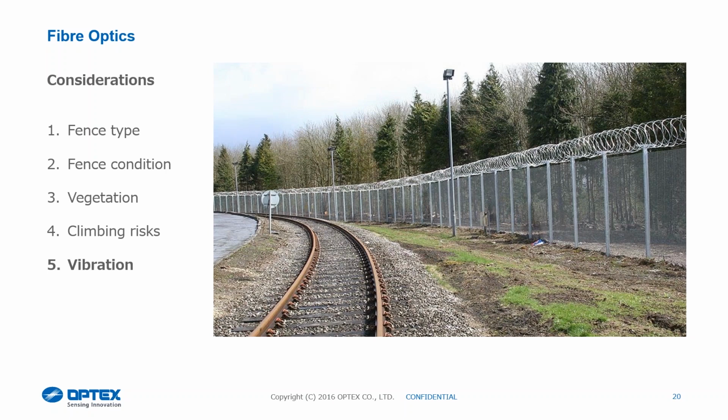We have had some sites where there have even been new fences installed but not installed to spec. On paper, if you're working on a site at design stage, you can specify a system, but when it's actually installed, if the fence line's not installed to the correct specification and there's a lot of movement, that's going to cause an issue. It can always be corrected, but you do need to do that survey to bear that in mind.